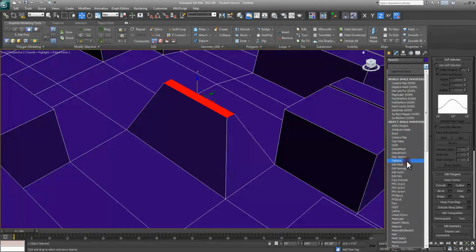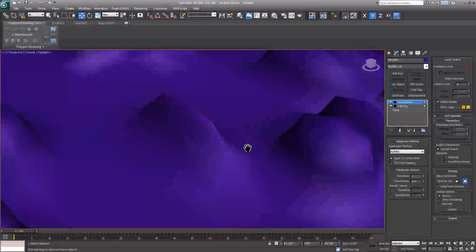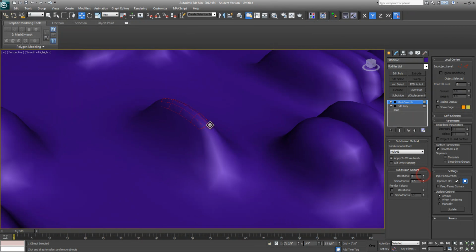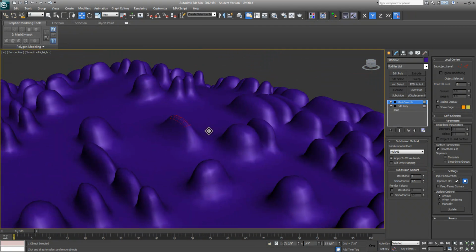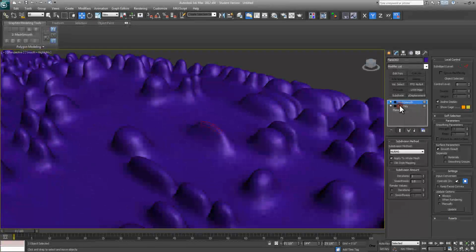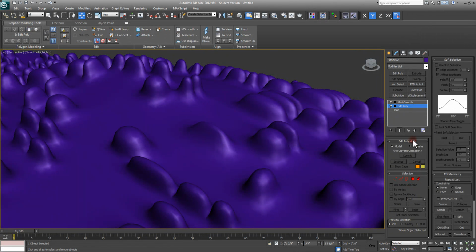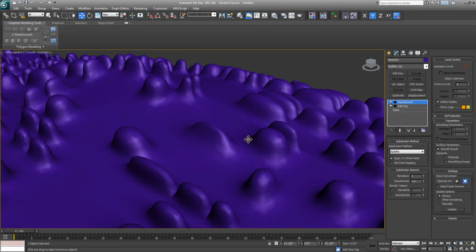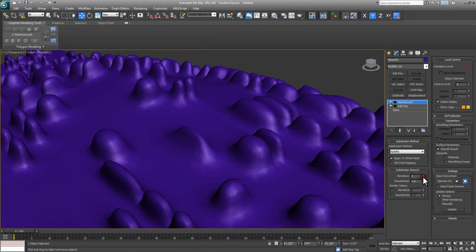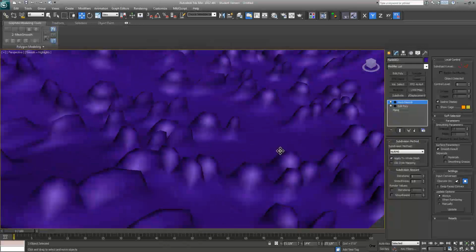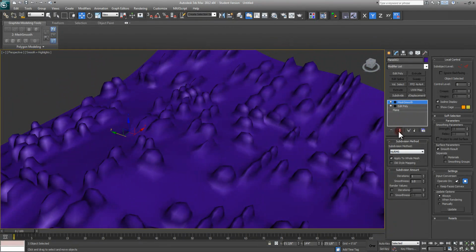you can see if I put something like a mesh smooth on it now, that geometry, when I go to the second level, is actually, and I have to deselect the polygon, because when I have the polygon selected, it's only affecting that area. So I want to deselect that and then go up to my mesh smooth modifier, just so I can see the effect on that.